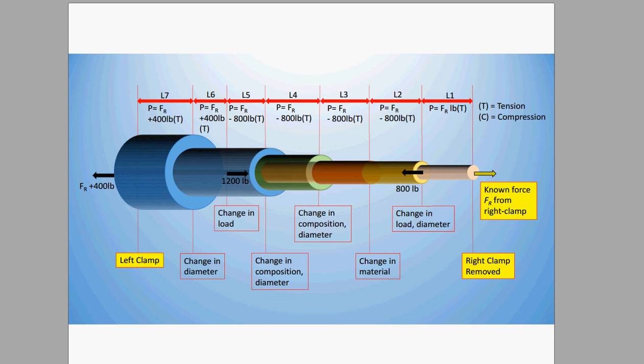This seems kind of confusing, but as long as you approach it in the step-by-step process, it will work out. You just have to keep in mind that when you're working with an indeterminate problem, the goal is different, where you're not necessarily looking for what the elongation is, because when it's clamped at both ends, you can't. There is no elongation then. Or if you have an example where it can only elongate, say, 1 millimeter before it hits a clamp or a wall, then you already know the amount of elongation there, and then it comes down to finding what the forces are in the clamps. So that's the process that we're going to work with for solving indeterminate problems. Hopefully it becomes a little bit more clear when you see the example problem.